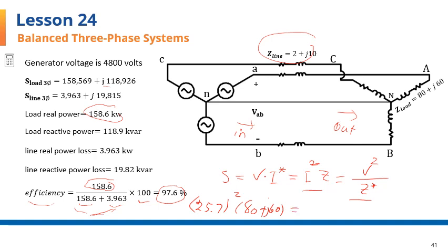And if you do it with this last form of the formula, you should get the same number, and that would be the single phase line-to-neutral voltage of the load squared, just the magnitude, 2570 squared, over the conjugate of the load, which would be 80 minus j60. And check your results and compare to the single line complex power, which would be a third of this one.